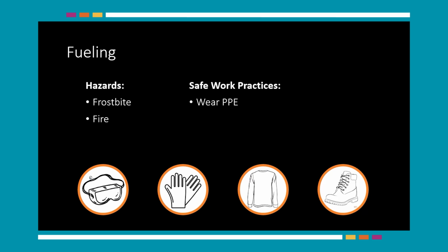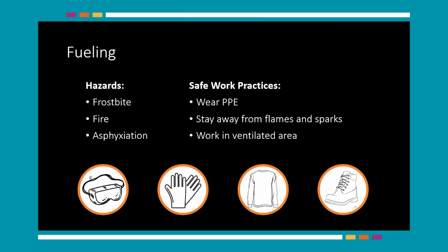Propane, like gasoline, is highly flammable. Do not replace the propane tank near any open flames or sparks. Since propane vapor displaces oxygen, large amounts of it can cause asphyxiation to those working in the area. Refueling should be done in a well-ventilated area or outside.